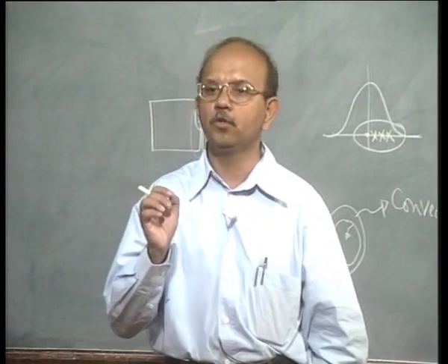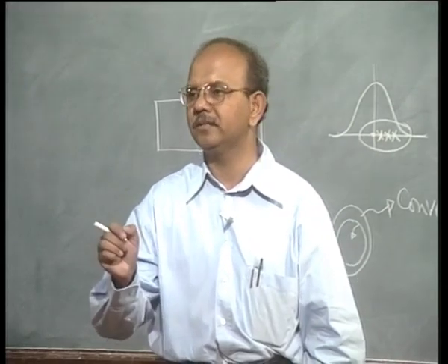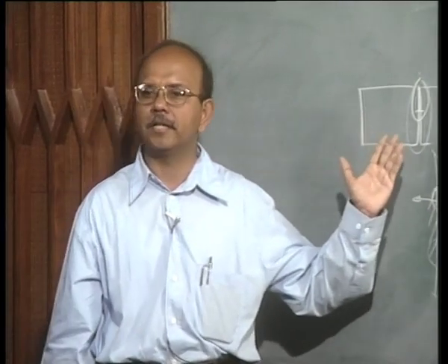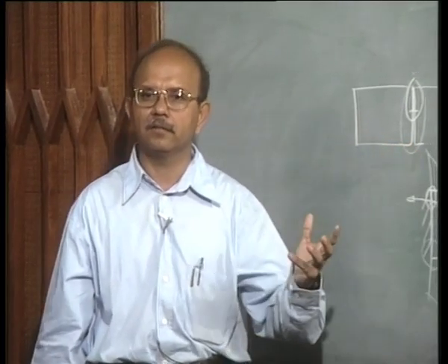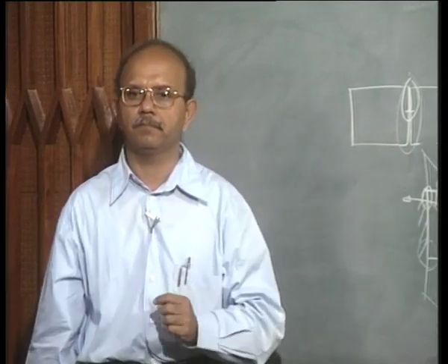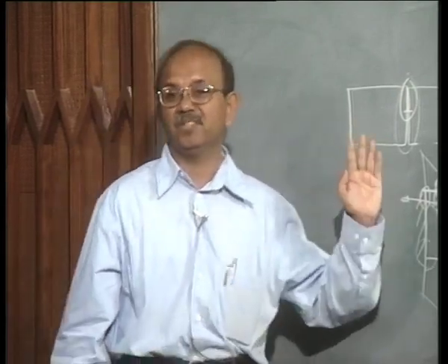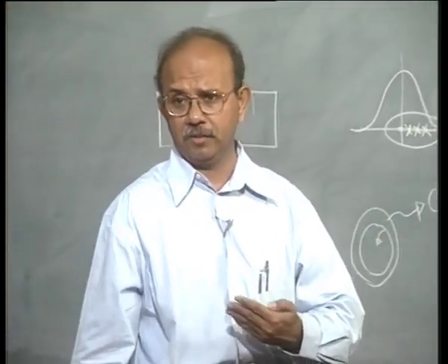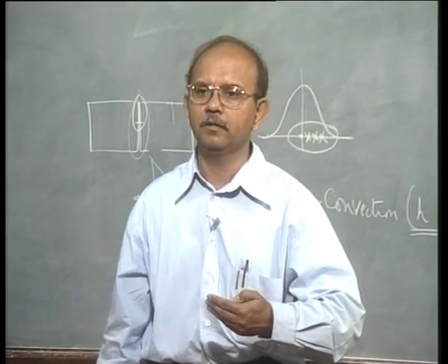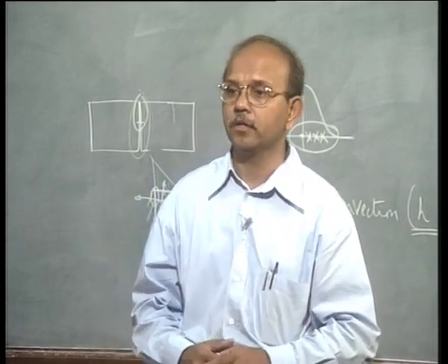You have to remove the rigid body motion, that has to be taken care of properly when you start. Maybe even the first node when you start welding, you may have to fix that node, the very first node in the very first time step. So please note that many times it may be required to change the boundary condition with respect to the steps. As you move further, it is possible to change the boundary condition.